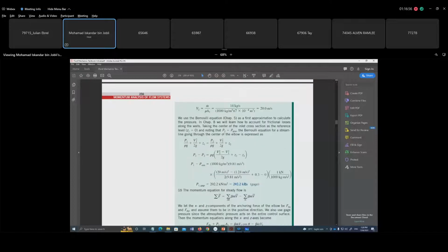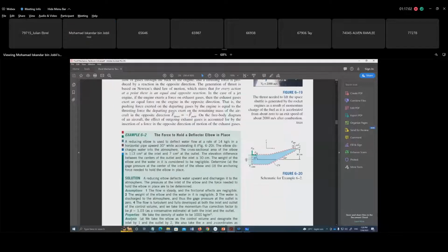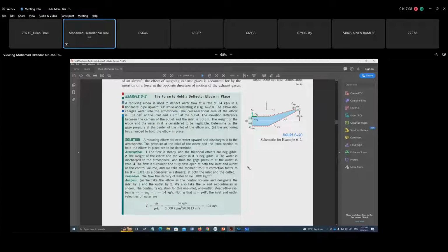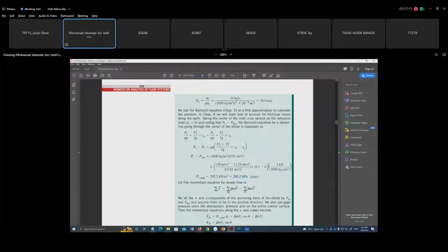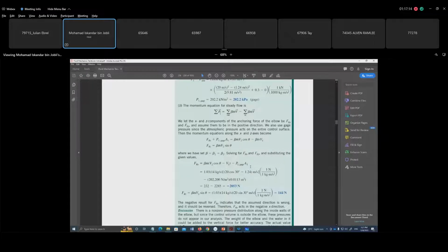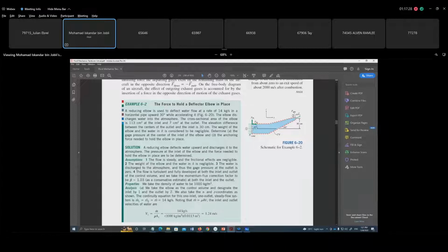Force number 1 is obviously Fx, going in this direction. That's the first force, and then plus another force in the x direction, with regards to the pressure. I think we just calculated that there's pressure on this side. There is P1 plus PATM in this instance. At point 2 you have pressure as well, it's just P2 equals PATM. This one is P1 plus PATM, and this one is just PATM.